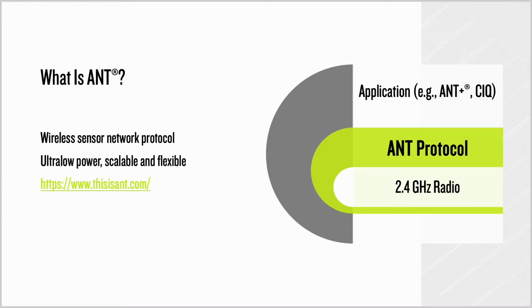ANT is also compact and highly optimized, designed for systems that are resource constrained, which is often the case in the embedded world. Low-level security features are built in. Finally, ANT is flexible and scalable. It supports many different network topologies, including peer-to-peer, broadcast, and star. Connections can be transient or maintained over long periods of time. You can find more information at thisisant.com.